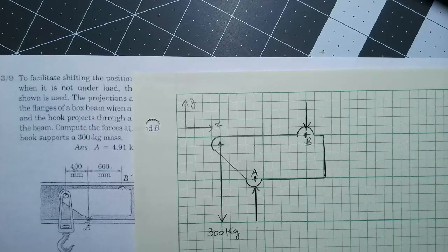When you get more complicated models that have multiple forces and reactions, a lot of times you end up guessing and you allow yourself to go through the equilibrium equations, and if you get a negative answer, you know that you have got an error and you got to switch direction. And oftentimes when you get into three-dimensional static analysis, it can get very complicated and you have to go back and redo all your equations. So the more complicated ones, we'll likely use a tool like MATLAB to figure out what the results of the equilibrium equations are.